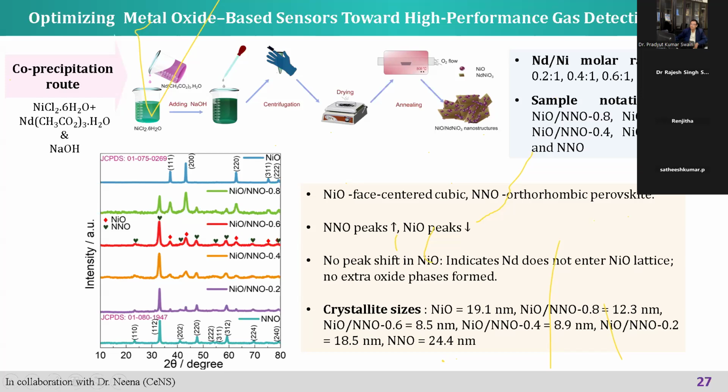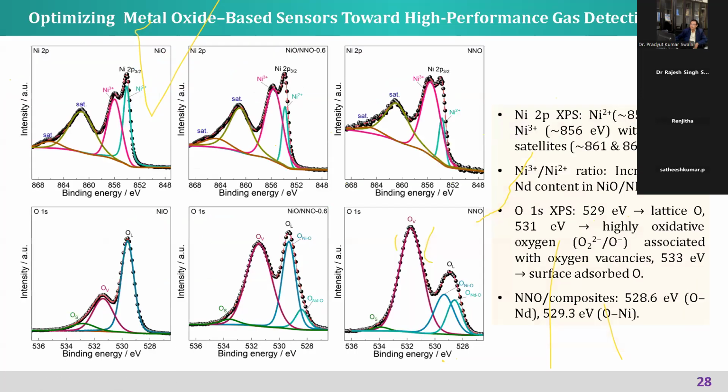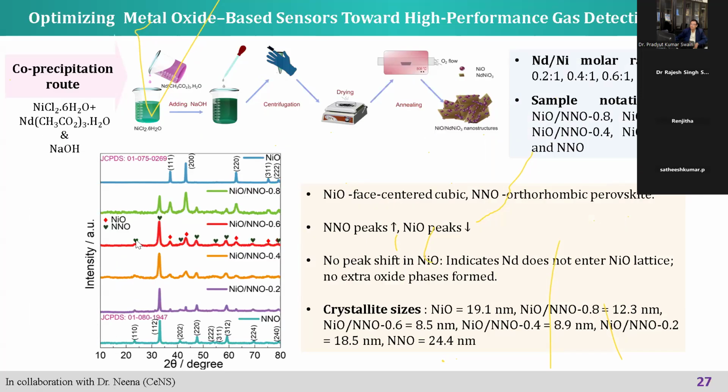We do the basic calculation of the crystal size from the X-ray peak width. There is a formula called the Scherrer formula, which is used. Using this formula, from the peak width of any X-ray peak, one can calculate the crystallite size.